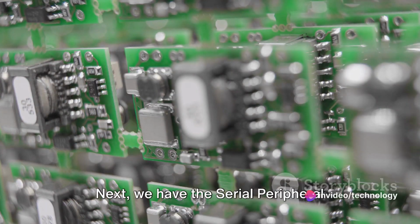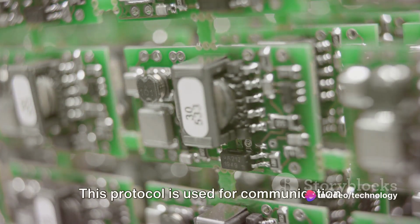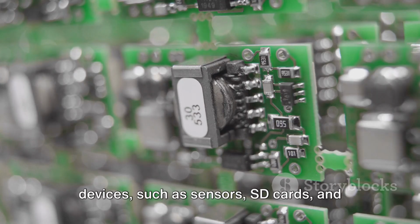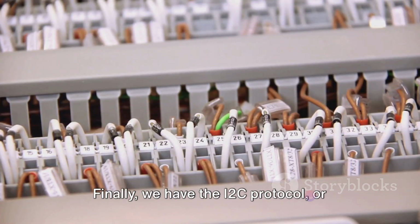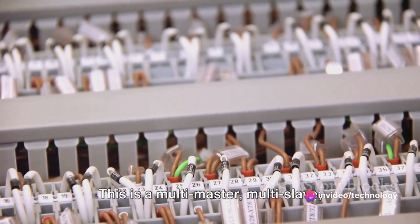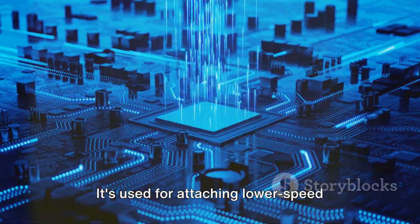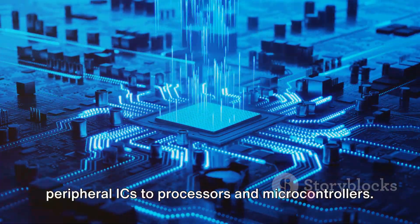Next, we have the Serial Peripheral Interface, or SPI. This protocol is used for communication between the microcontroller and peripheral devices, such as sensors, SD cards, and shift registers. Finally, we have the I2C protocol, or Inter-Integrated Circuit. This is a multi-master, multi-slave, packet-switched, single-ended serial computer bus. It's used for attaching lower-speed peripheral ICs to processors and microcontrollers.